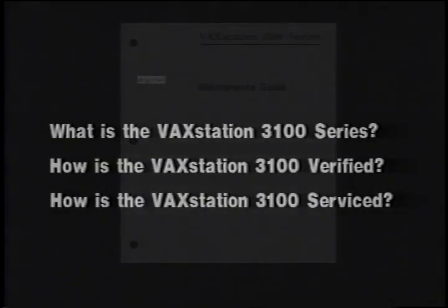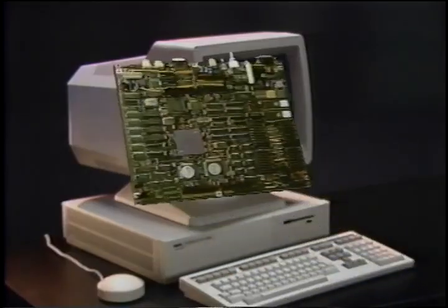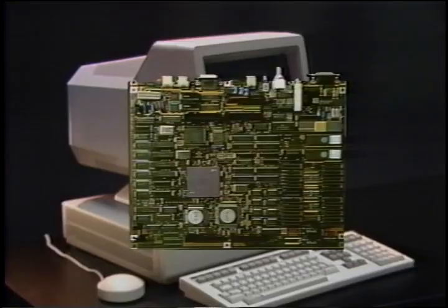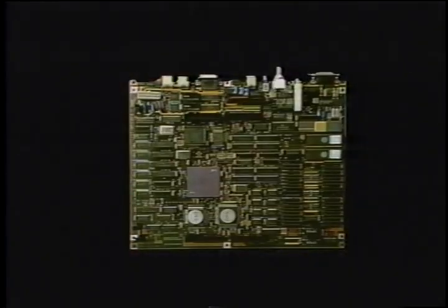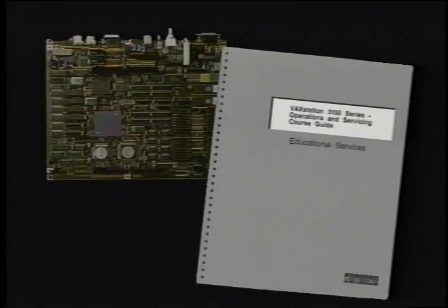If you viewed all 3 video segments, complete the course test, fill out the student opinion form, and then proceed to the hardware lab. The lab may have a different version of the VAXStation 3100 than is shown in this video. Your lab exercise is to remove and then replace the KA42 system module. Feel free to also remove the power supply or any disk drive. Complete the course by verifying normal operations so the next person to perform the exercise has a working system.